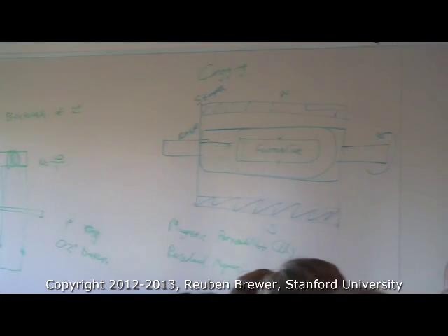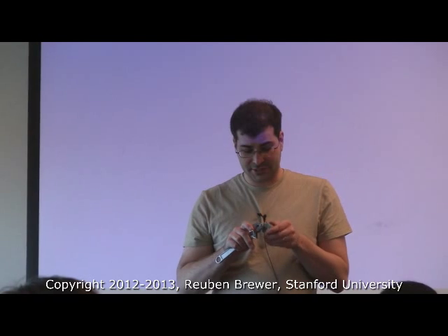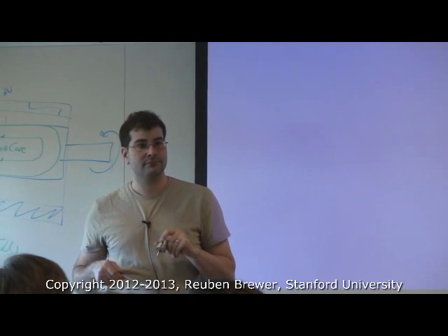So this is a backdrivable motor, very easily backdrivable. And it's shitty, so I guarantee you the cogs are pretty wide apart. And yet you can't see any cogs. So I could use this just fine on my robots without any problems. So at some point you still have a nice backdrivable compact motor where the cogging isn't bothering me at all. That's why. It just becomes part of resistance.